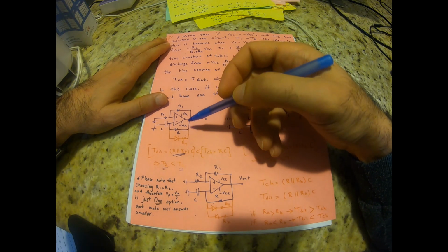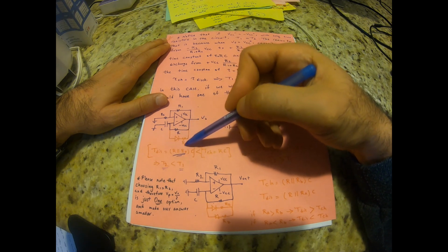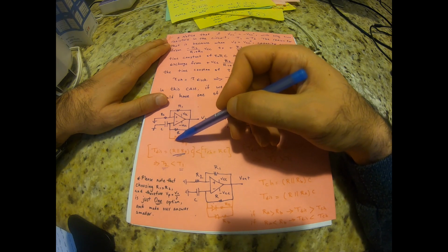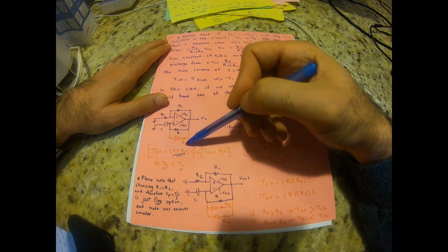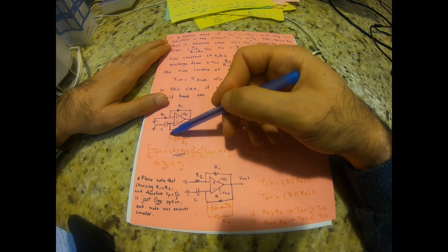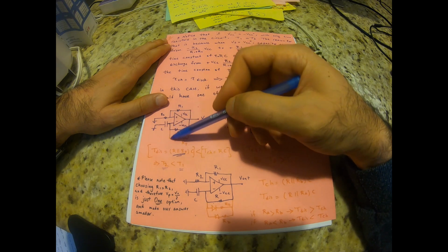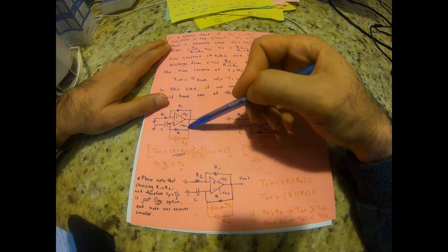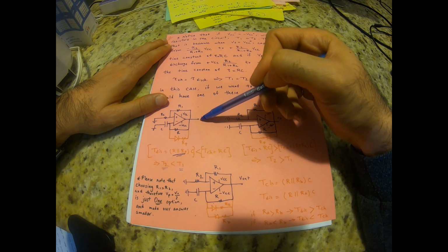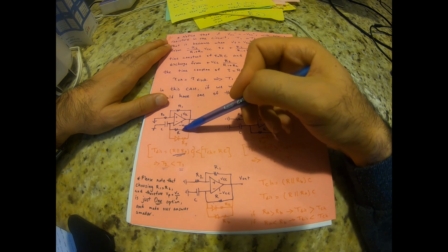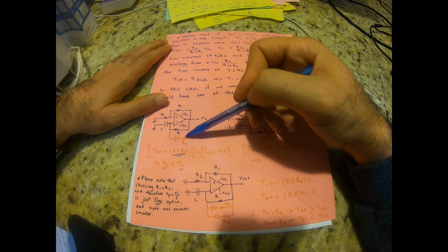So what happens if I add another resistance here with a diode? It means that this is like a directional resistance. It's only going to be in the circuit if the current is going from ground to V out, right? So when does this happen? When the capacitor is discharging. How about when the capacitor is charging? The current only goes from the R resistor to the C. This one is going to get blocked.